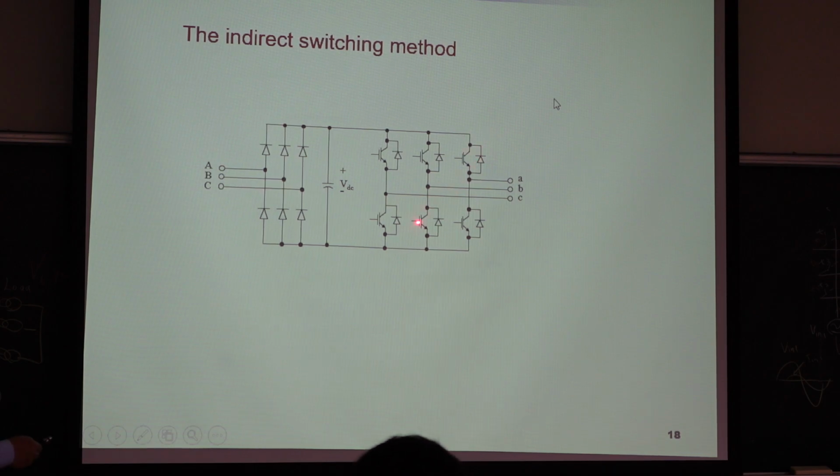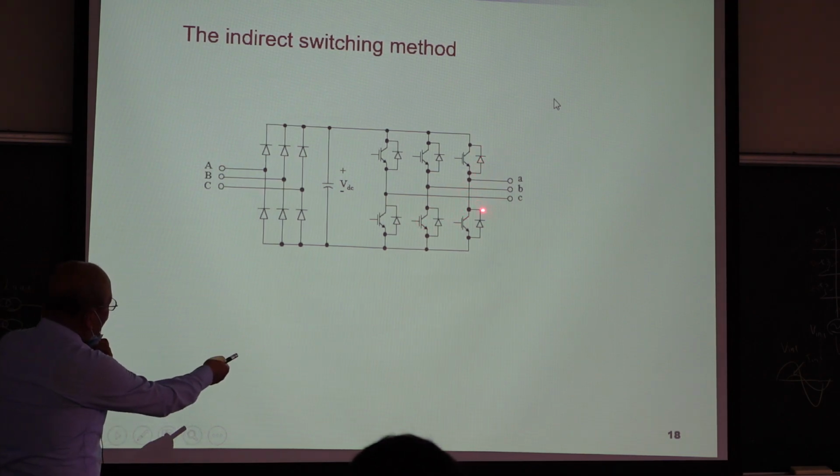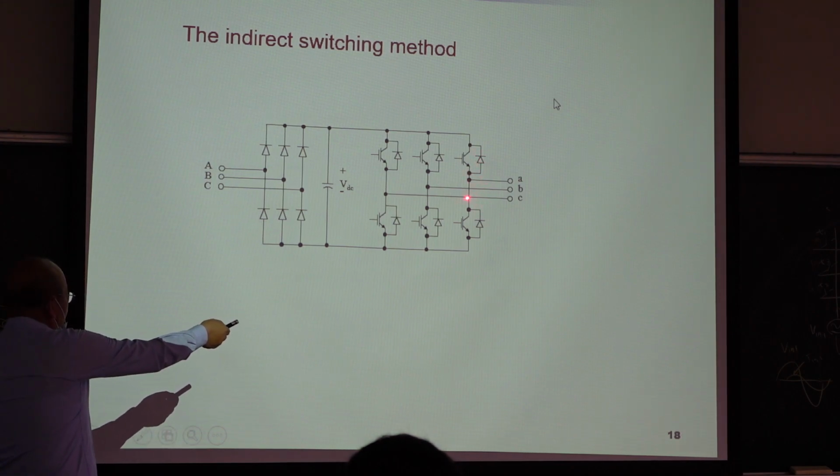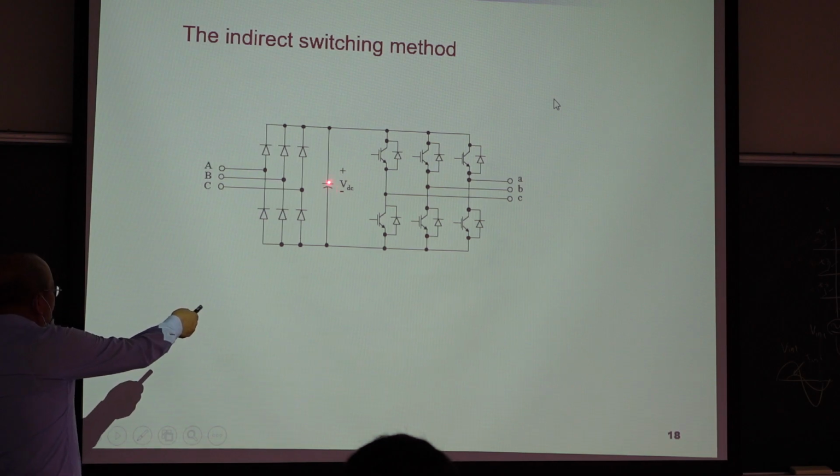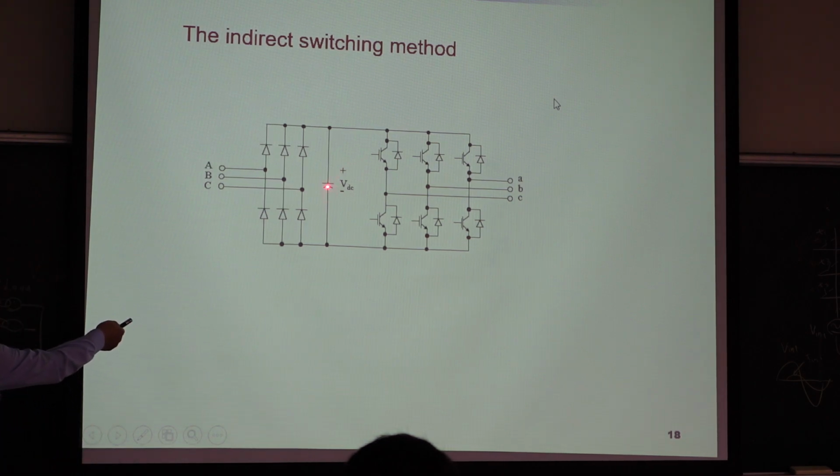How about the energy regeneration? If I want to recover the energy, then I can have energy to the DC bus. Then I want to move the DC energy into the grid, but we have a diode. Can I go back? No. But here, from input power to output power, we can regenerate, we can recover output power into input.